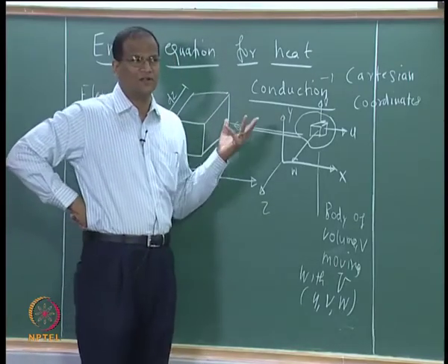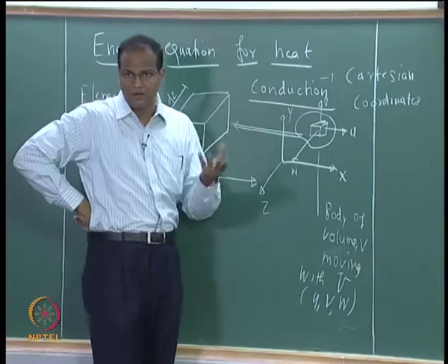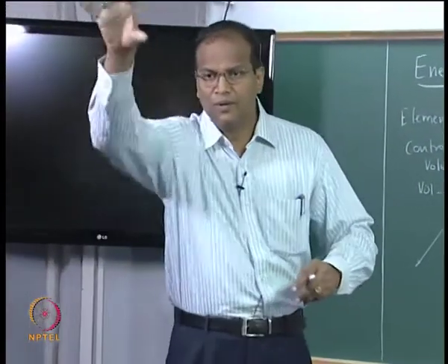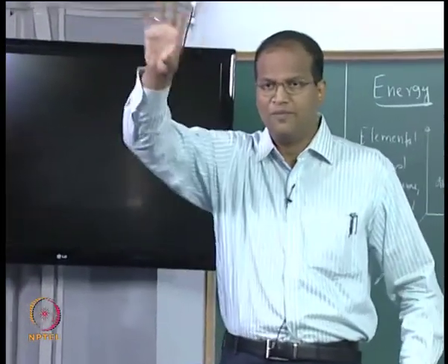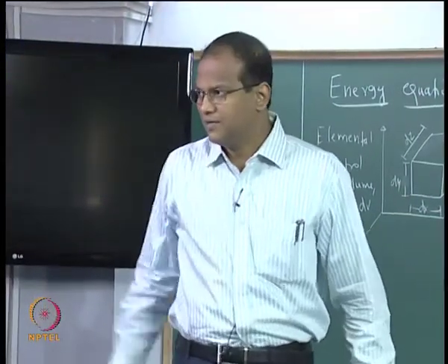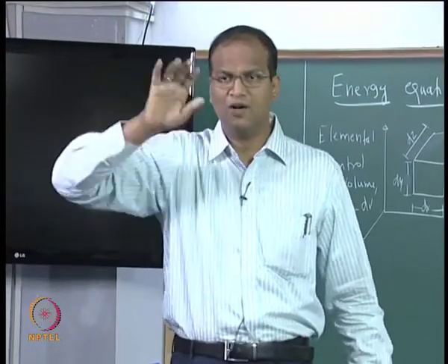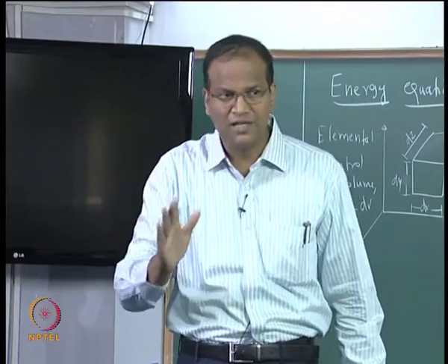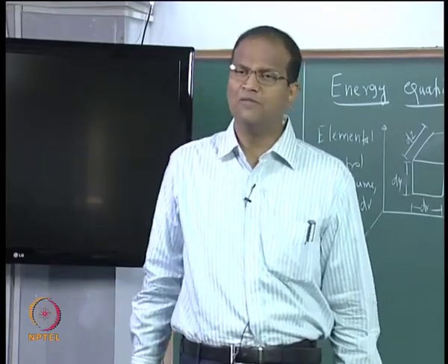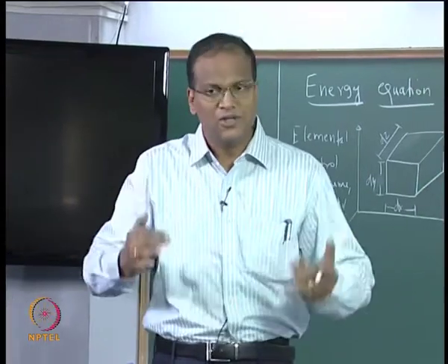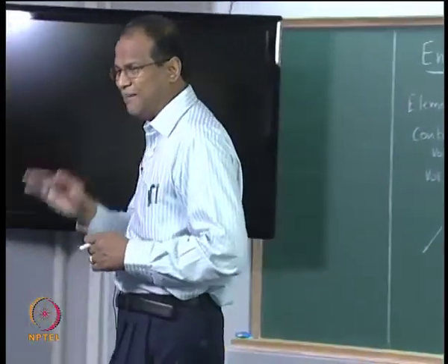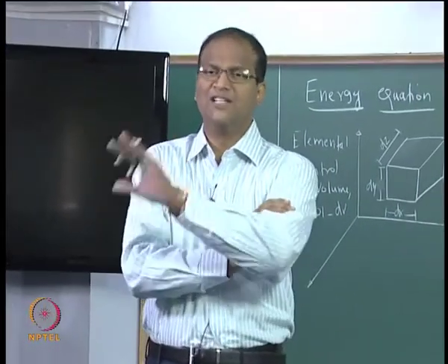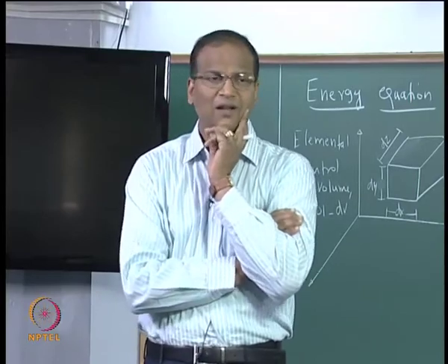Sir, why do you want to have a moving body in conduction? I told you welding rod problem or moving heat source problem, or some bullet or cannon is fired, that source is also moving, okay, or welding rod is moving. So, we have to derive the heat conduction equation in its most general form, and then in many cases we will say this velocity is 0 and reduce it for the stationary case, because 99% of the time it will be the stationary case, but we should have a general equation to cover the cases where the body is moving.